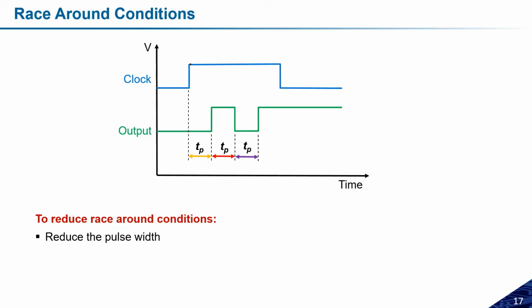Maybe with the clock width we have considered, the output changes at a particular time and then changes again. So this may create the problem. Even though we reduce the clock width to overcome this problem, it cannot be overcome 100%. Also you need a high frequency clock pulse, and designing an infinite frequency clock pulse is not possible. So the other alternative is the edge triggering I just told you.